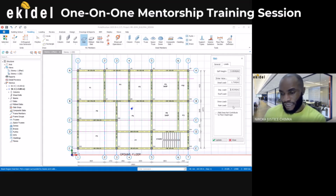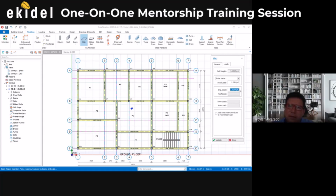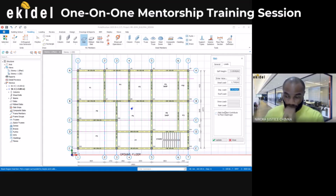I think they used to activate it somewhere. I think maybe after, I'll show you how to activate that. Okay, but apart from that, this is the load that you need. Then once you've done that, it says slab does not contribute to diaphragm. Yes, don't check it. Okay, don't check it.